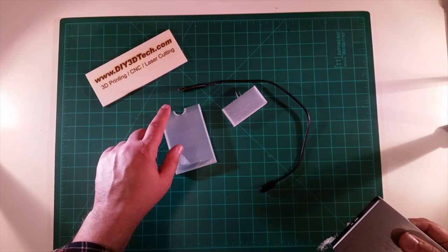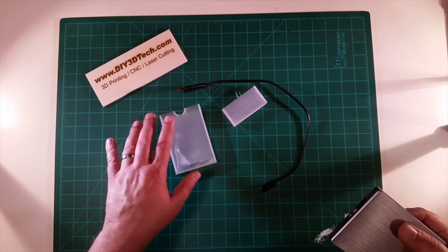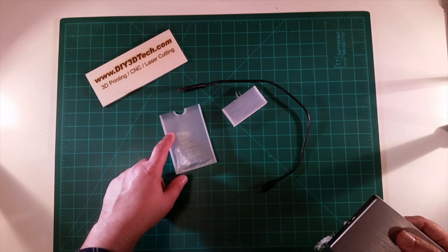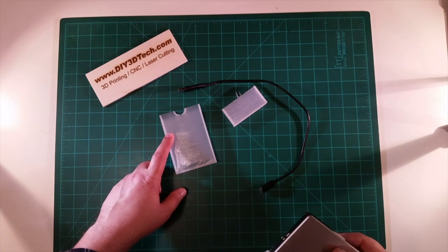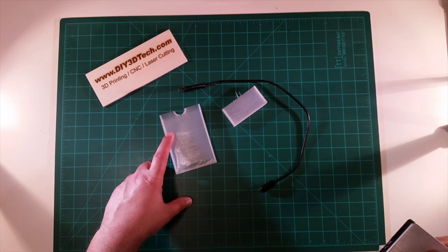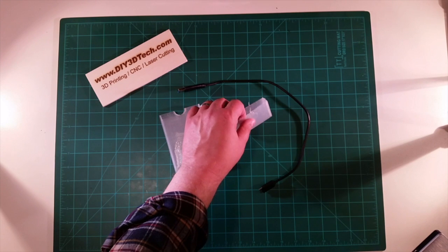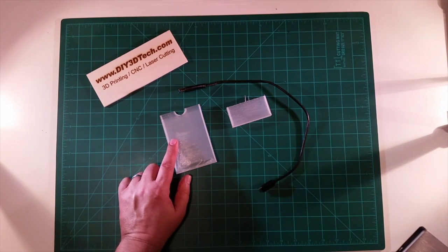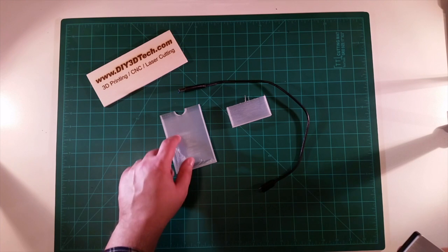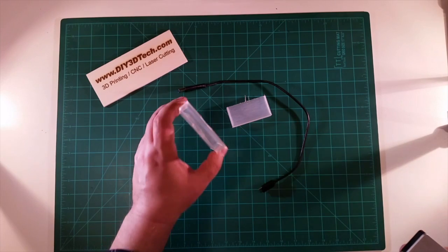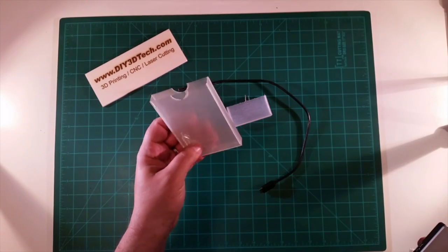And I think if you're going to do this, now this is more of an opinion, I would probably print at a multiple of the nozzle diameter. So the nozzle diameter is 0.4 millimeters. And so this one, I think, came out at an odd number, and I think 1.5 came out better. I think even printing at like a 1.2 or 0.8 would probably be better, but I think maybe 1.2 would be about the best, because this is 1.5, and this came out pretty good other than this blob.